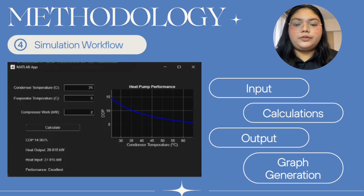Lastly, the simulation workflow. The simulation begins with user-defined input parameters through an interactive graphical user interface, GUI, which is developed using the MATLAB application. These input parameters include the condenser temperature, evaporator temperature, and compressor work. With the provided inputs, the program calculates the COP, QH, and QL. After the calculation is complete, the program generates a graph of COP versus condenser temperature.